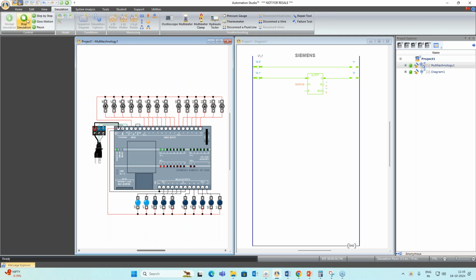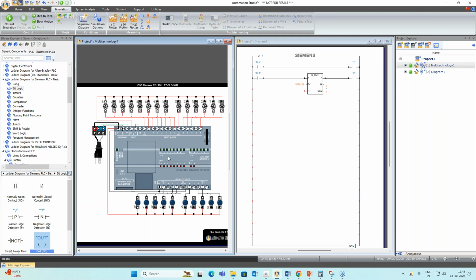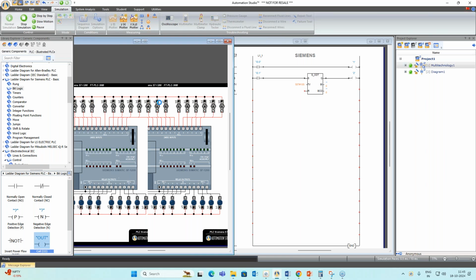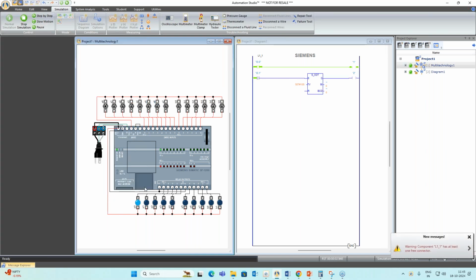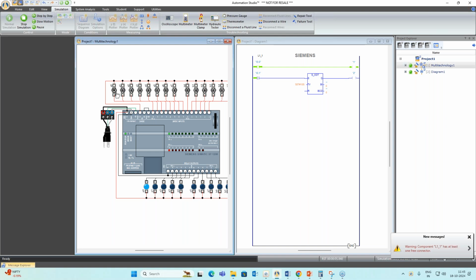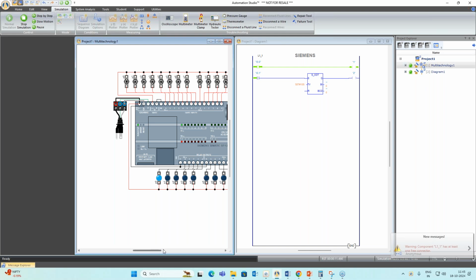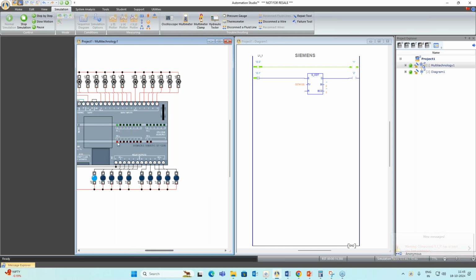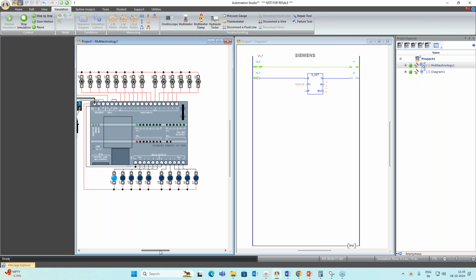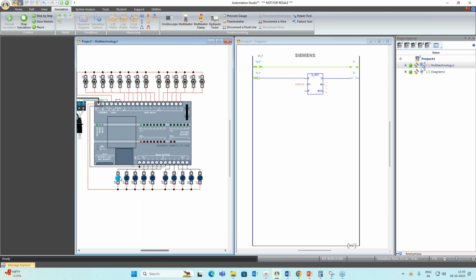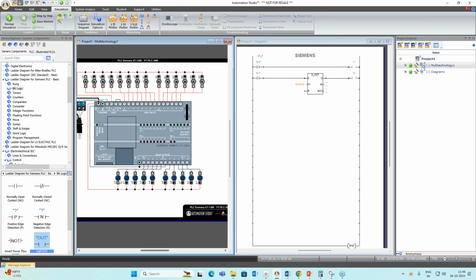Not only this, but all PLCs have that functionality, to show the status of that particular output or input. So on the PLC you can also see the status, as well as on the output or input. If I click on A0, my logic is getting transferred and this A0 lamp is also glowing. But sometimes the lamp will not glow, but the out will give you the status that it is activated. So anyone can understand that there is no issue from the PLC, but from the lamp there may be some issue. You can see the settings for the lamp, because for every lamp we have a voltage rating, min and max rating. That can be set according to the need.